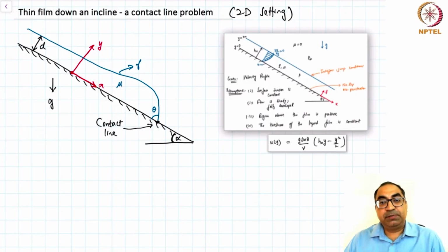In the previous lecture, we looked at the problem of contact angle hysteresis, and we found that when we have contact angle hysteresis, the contact angle can be different from the Young's angle. So we described this angle in terms of two angles, the advancing angle and the receding angle. And we said that in general, you will have an angle between these two extreme limits, but for a static problem.